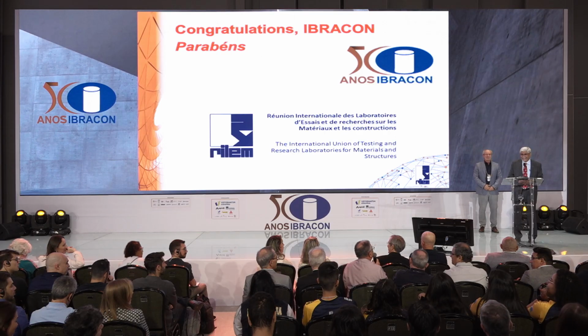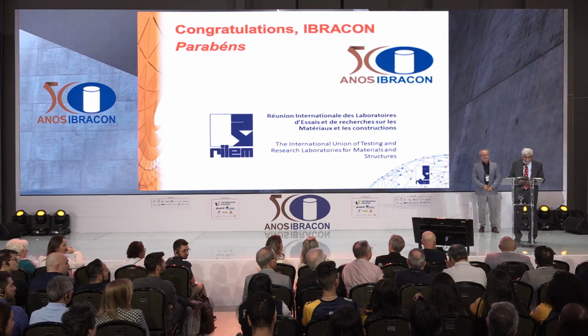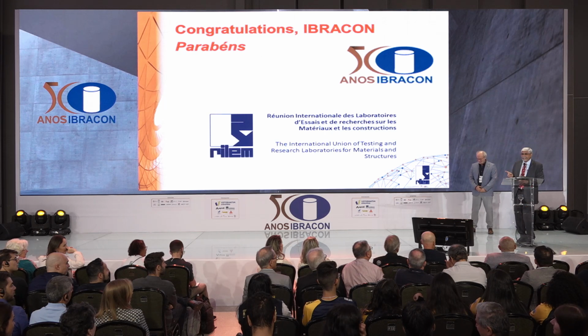The limestone has to be finer than the clinker? The fineness, the blend. It has to be almost the same fineness as cement. But usually what happens is when you grind clinker, the limestone becomes fine because limestone is usually softer. So actually what we find is the fineness of the LC3 cement is more than the fineness of ordinary Portland cement because the clay is easy to grind.